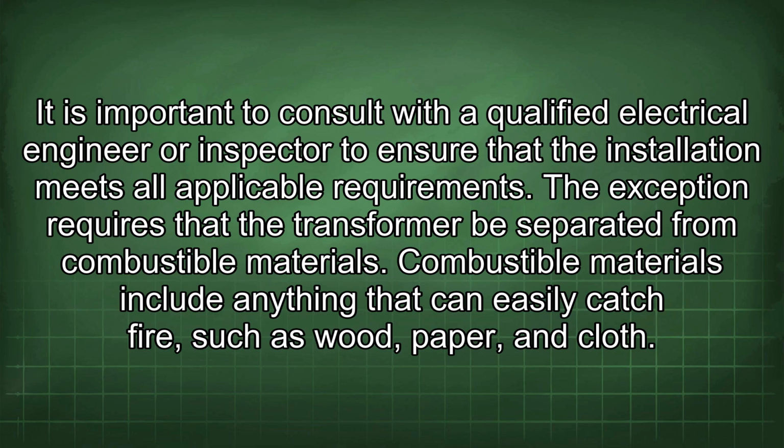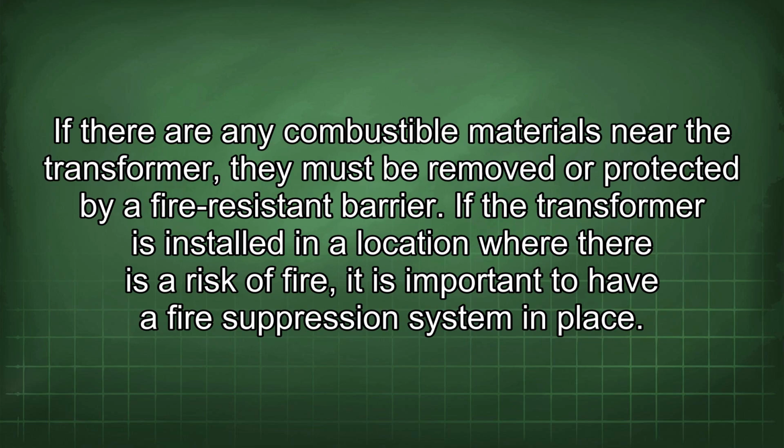requirements. The exception requires that the transformer be separated from combustible materials. Combustible materials include anything that can easily catch fire, such as wood, paper, and cloth. If there are any combustible materials near the transformer, they must be removed or protected by a fire-resistant barrier.